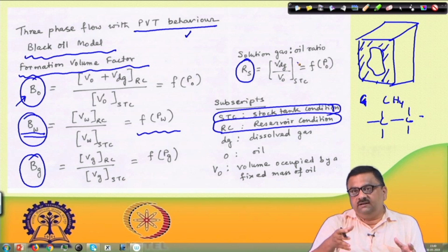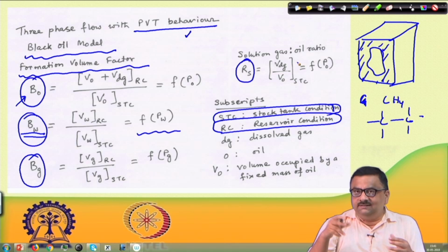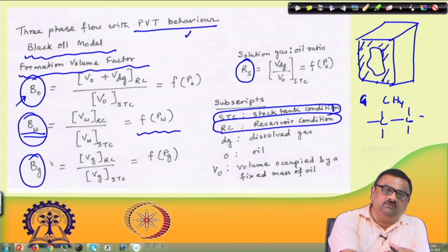But now in this case we have 3 phases sitting in the porous medium, oil, water and gas, and now I am having a flow, and maybe a withdrawal from some point. When you generalize this, obviously there would be either injection or production of either the oil phase, gas phase or water phase. So, one has to write a general equation, and we have to write 3 continuity equations, mind it, one for the oil, one for the water and one for the gas. And obviously, there would be an accumulation term, and that accumulation term will only talk about SO, SW, and SG. In fact, you need only 2, because SG would simply be 1 minus SO minus SW. How much would be the density change, we are leaving to the formation volume factor.